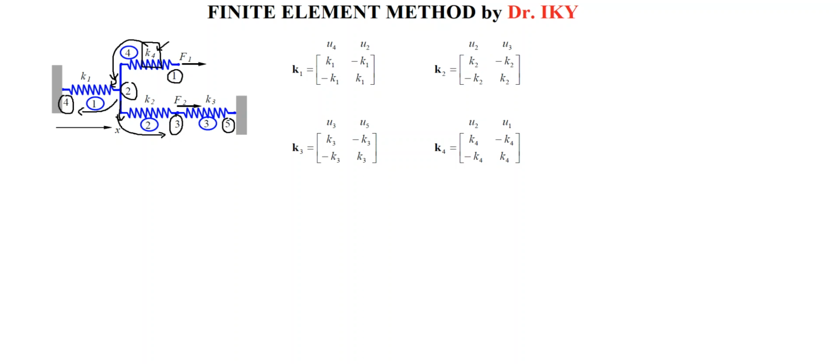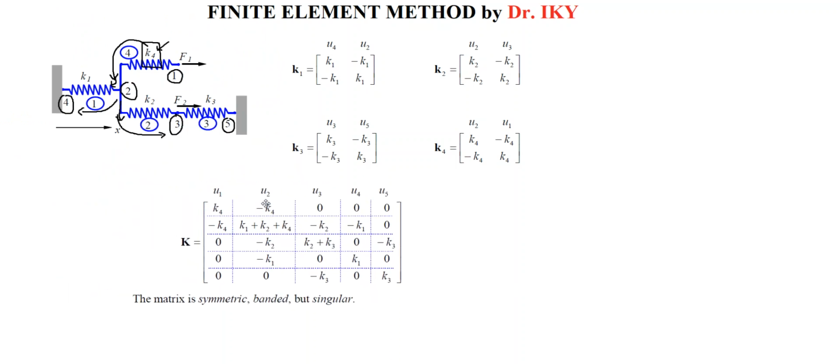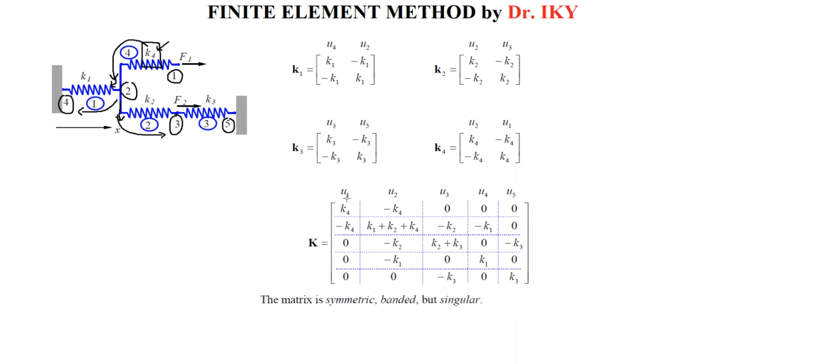Considering this one, we have to create our superposition method and apply a global stiffness matrix, or combine from these ones and apply a global stiffness matrix. I don't want to spend much time. Because of that, I'm going to put the original solution document here. So you are going to start with K4. Let me mark all of the defining areas. K4, and you will continue with minus K4, and here should be plus K4.